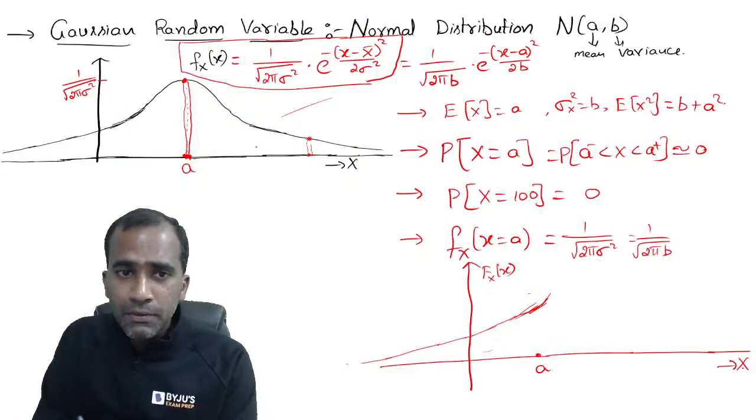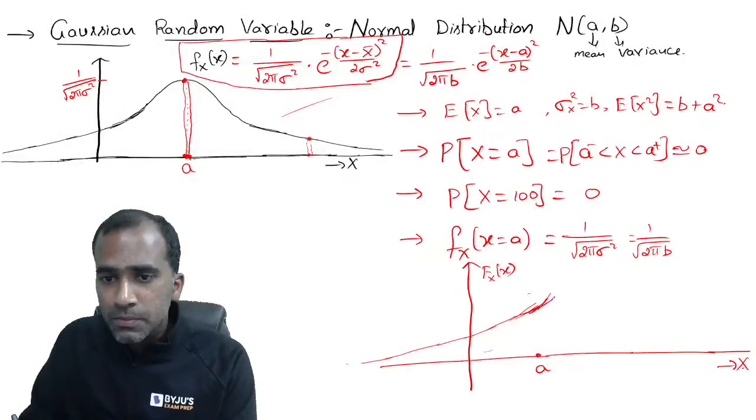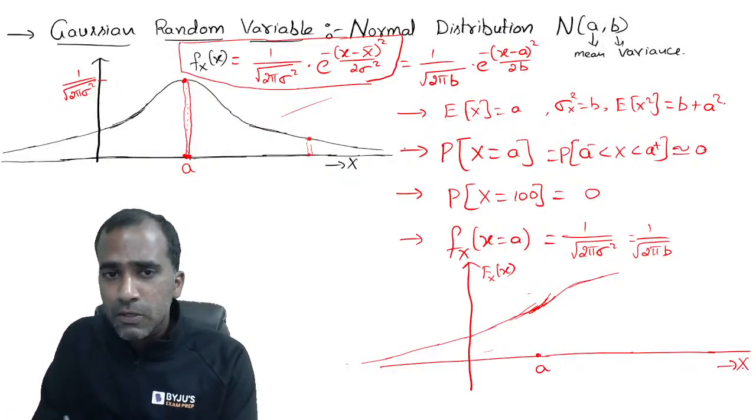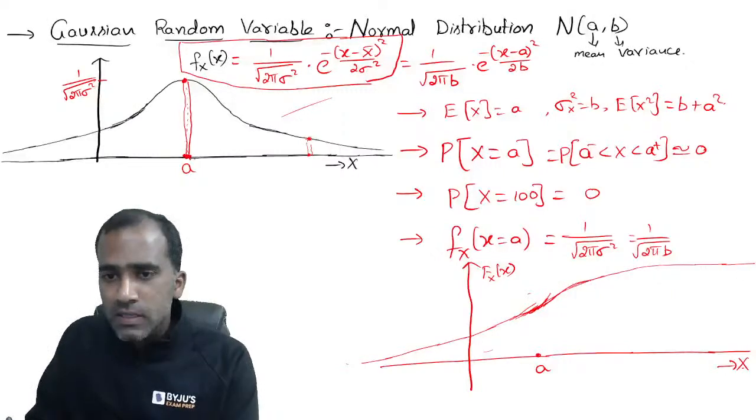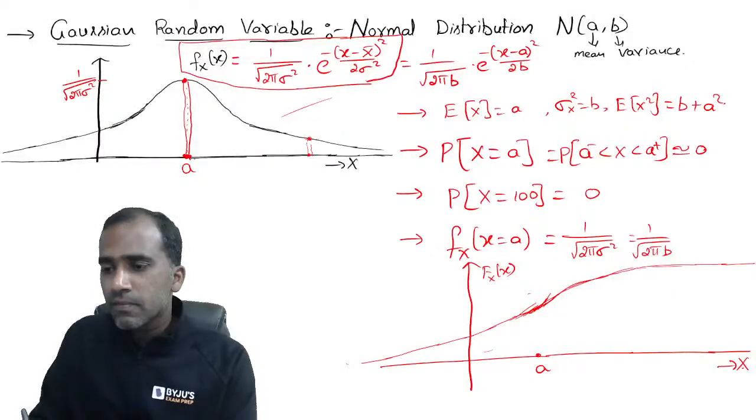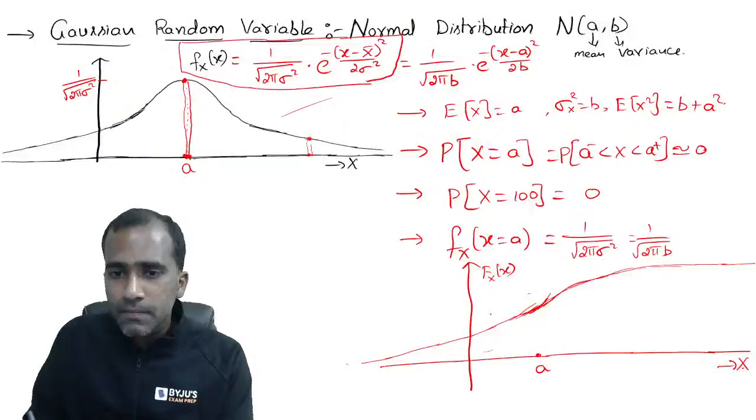And after that, the amplitude decreases, the slope also decreases. See the slope? Am I decreasing the slope or not? And slowly the slope goes to 0 because the amplitude here goes to 0. In the integrated signal, slope should go to 0, which means it should become constant. This is how the CDF looks for a Gaussian PDF. Just with common sense, you can plot it. The height at A, yes, very good Deepak.